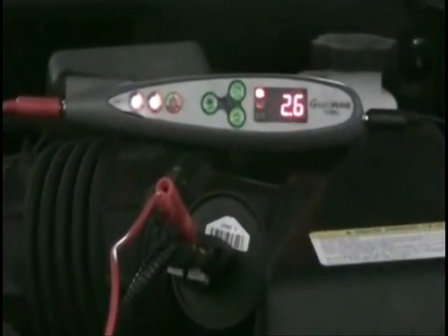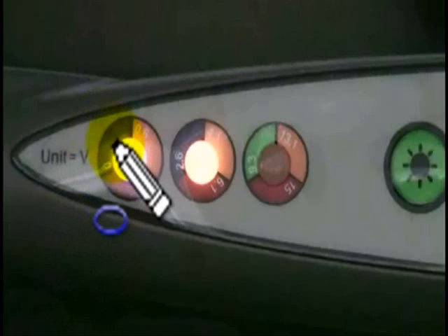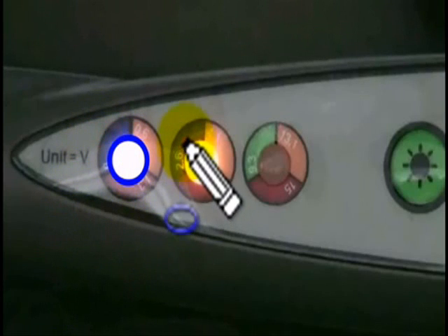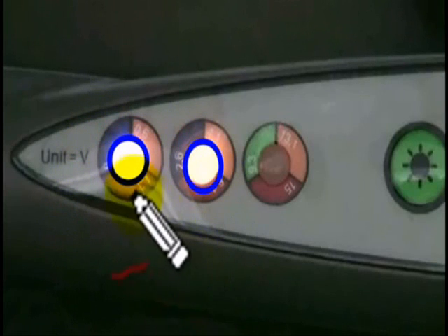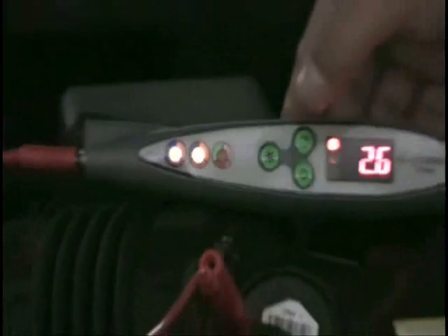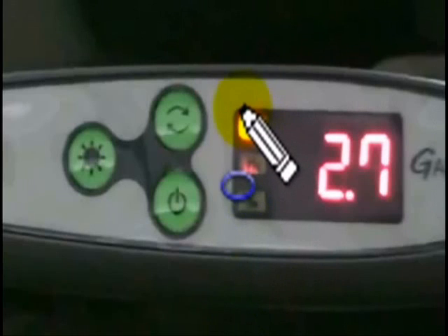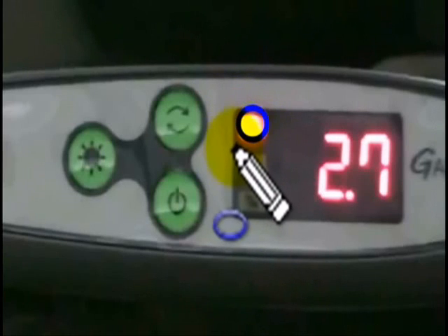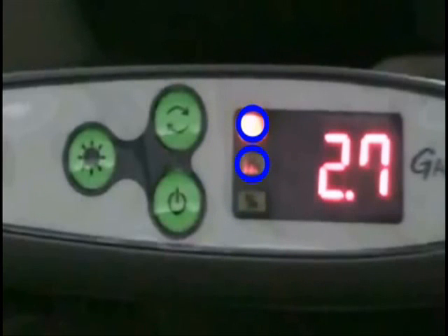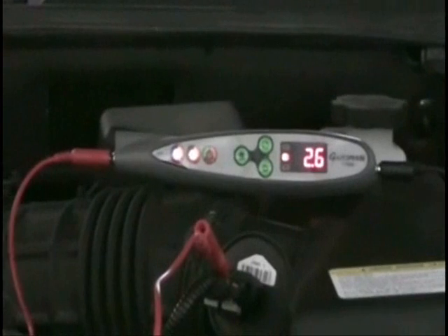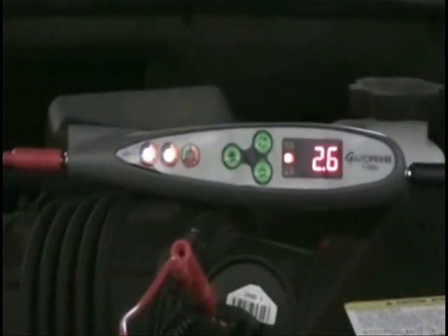This is mass airflow sensor. Airflow sense has pulse from ground to 5 volt as you can see. Push the select button and you can check frequency of airflow sense pulse after changing mode from voltage, which is the default mode, to frequency. Frequency means the number of pulses in 1 second, and its unit is hertz.